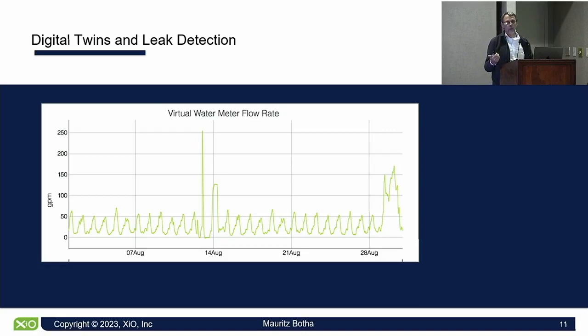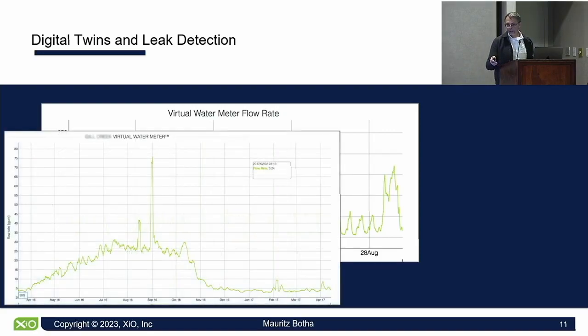First, you have to be aware. So if it's not obvious on the ground where you see the water seeping out, you only know that you have a leak when you get your next electricity bill. So suppose it takes 30 days for the bill to get there. You may have had a leak for 6 weeks, and you didn't know, but your pumps were running all the time, and you didn't notice because you didn't have full-time staff at your site.